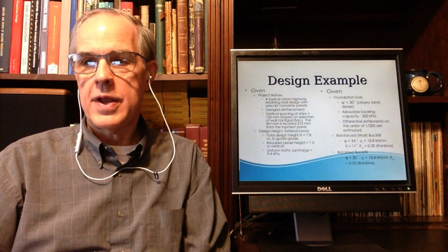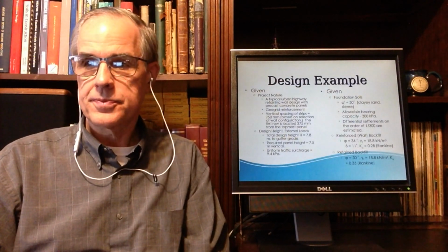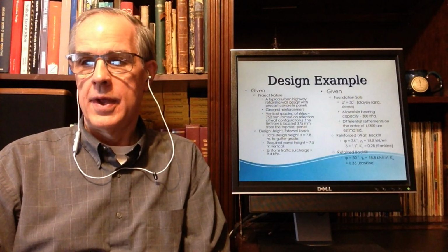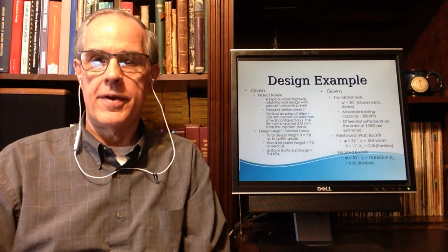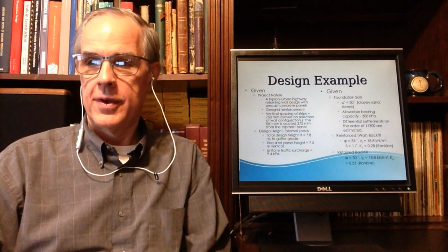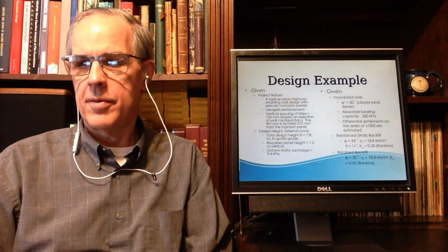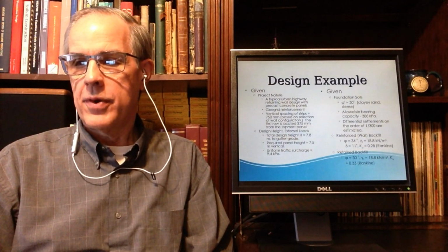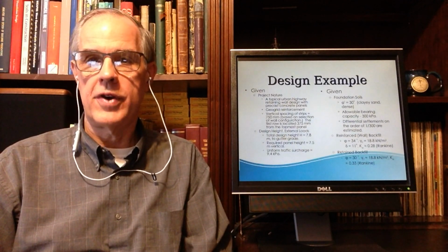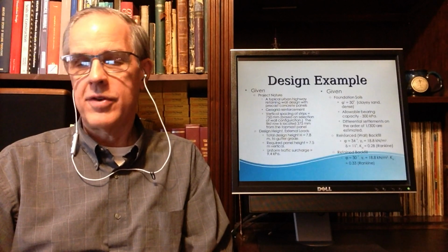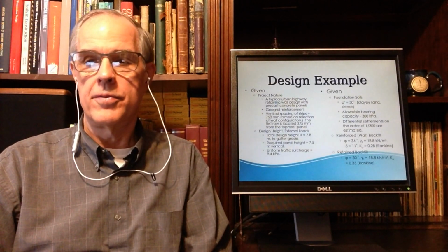There are 3 soils. First, the foundation soil, the soil under it, has phi of 30 degrees, and we're not going to worry about the other 2. The reinforced backfill, the backfill inside the strips, has a phi of 34 degrees, a little gravel in there probably, and unit weight 18.8 kilonewtons per cubic meter. The delta is equal to 11, that's for the friction. And the Ka, I go ahead and compute it as 0.28. You can verify that that is true.